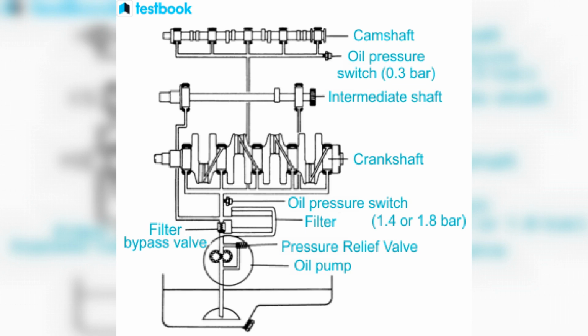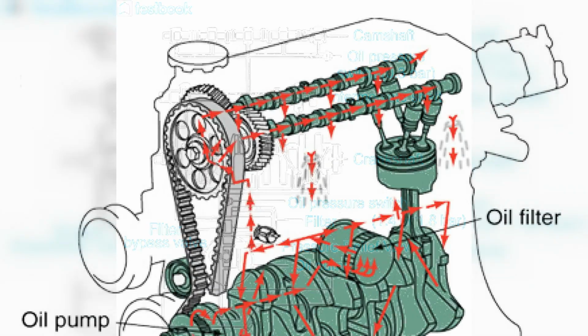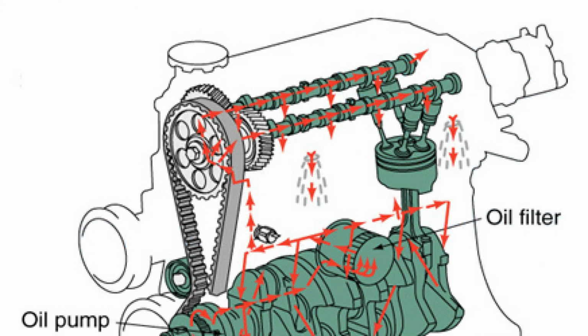The splashing due to the high speed of rotation of the parts is so intense that an oil mist is formed, which envelopes all other parts of the motor. Subsequently, under the influence of Earth's gravity, the lubricant condenses and flows down into the crankcase pan, thus closing the cycle. The above scheme is the most popular and is called wet crankcase lubrication.